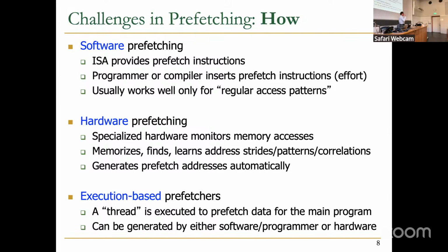There have been many works on this topic, and this is an area that I've worked on personally for more than 25 years. As I mentioned, my first internship at Intel actually was tuning their prefetcher that they had, and I'm going to talk briefly about what kind of prefetcher they had, and also looking at what kind of accesses should be sent to the memory controller in what order from the prefetcher. So how do you order the demand and prefetch accesses on the processor chip such that you get a good access stream on the memory controller, such that you get good row buffer hit rates, for example.